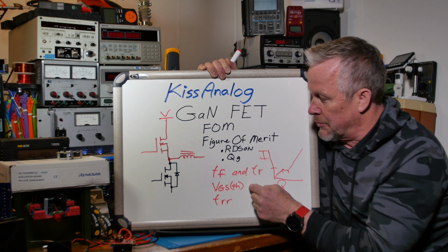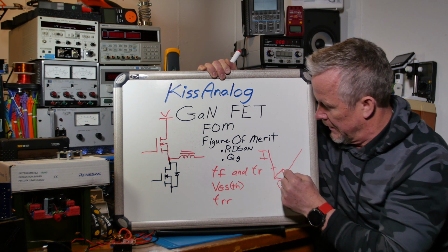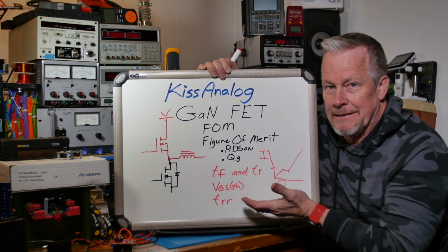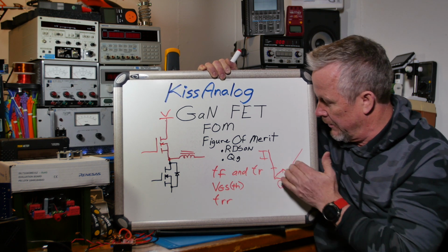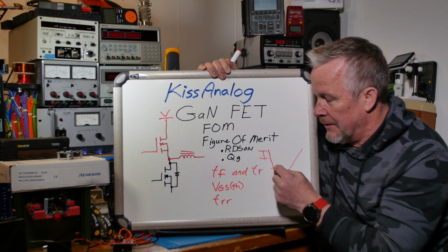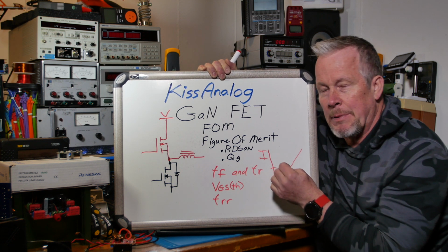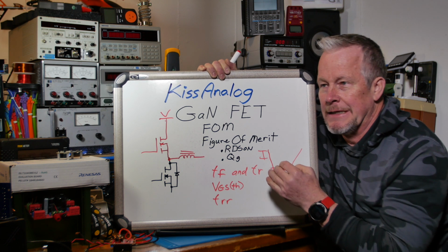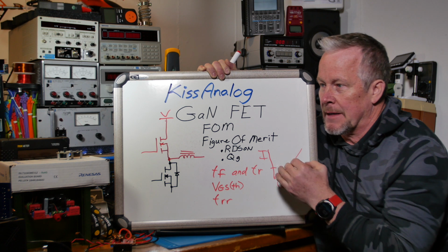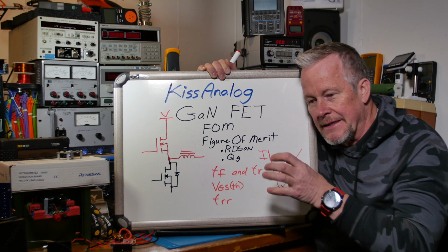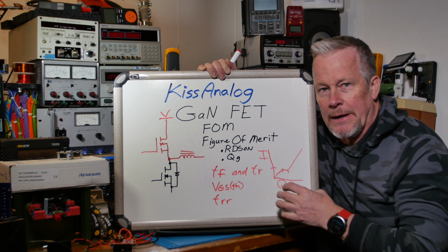The gate source threshold, this little charge thing, is usually short, because that's the beauty of them. You can turn them on fast so they don't have a lot of charge, okay? Well, let's just talk about this gate source a little bit. With more powerful FETs, it used to be that you had to have a higher voltage, say 10 volts on the gate, to make sure that it was fully on, that faucet turned all the way on, okay?